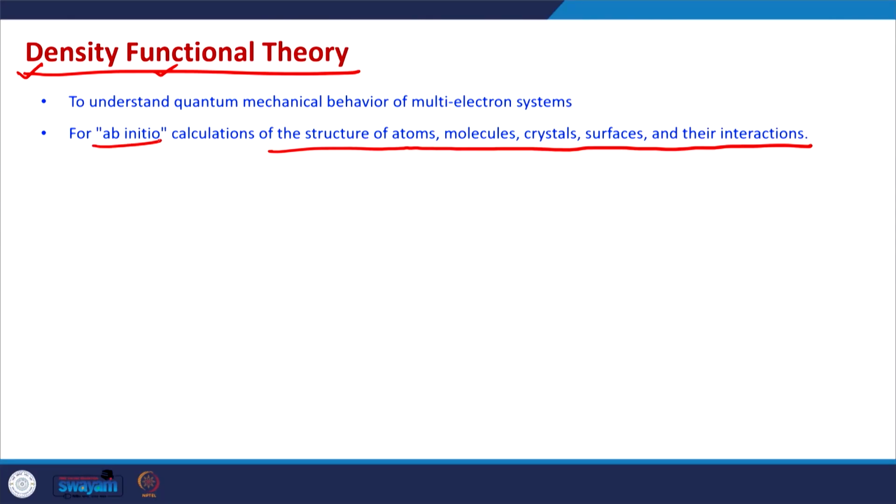Because in our previous discussion, what we have assumed is that we know the band structure of the device, the band structure of the channel, and from that we can calculate the density of states. From there we can calculate the modes, the current, almost all the electronic characteristics of the device.